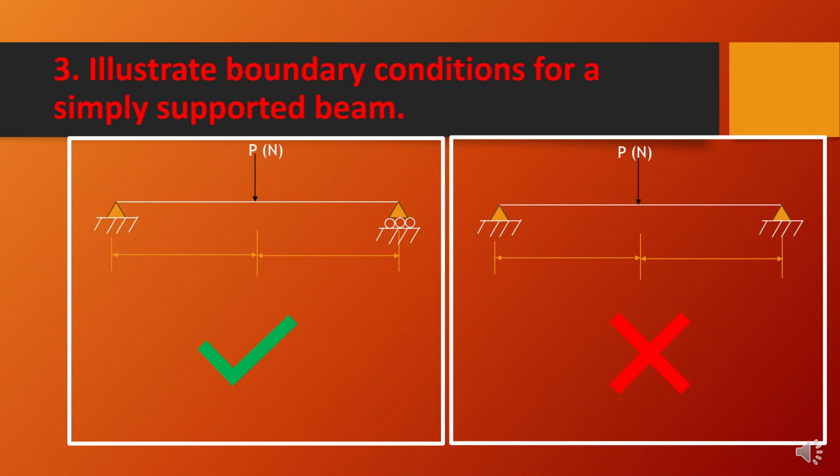In a linear analysis, both these boundary conditions will give the same result, but if you switch on the geometric nonlinearity, it will be different. The usual intention of the analysis is what is given on the left, so we must be careful in telling that.